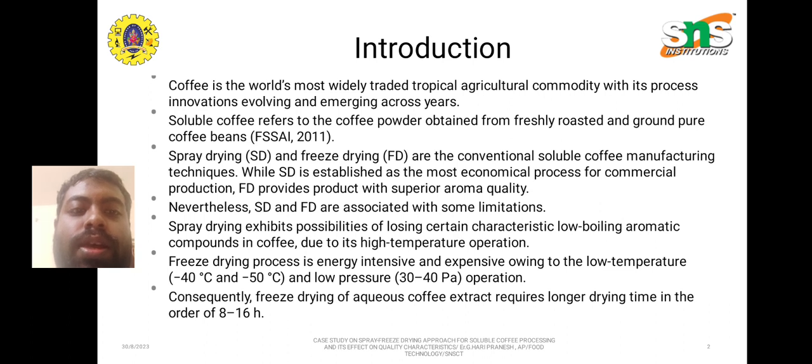Spray drying exhibits possibilities of losing certain characteristic low boiling aromatic compounds in coffee due to its high temperature operation. The freeze drying process is energy intensive and expensive owing to its low temperature, that is minus 40 to 50 degrees Celsius, and low pressure, 30 to 40 Pascal, operation. Consequently, freeze drying of aqueous coffee extract requires a longer drying time, in the order of 8 to 16 hours.